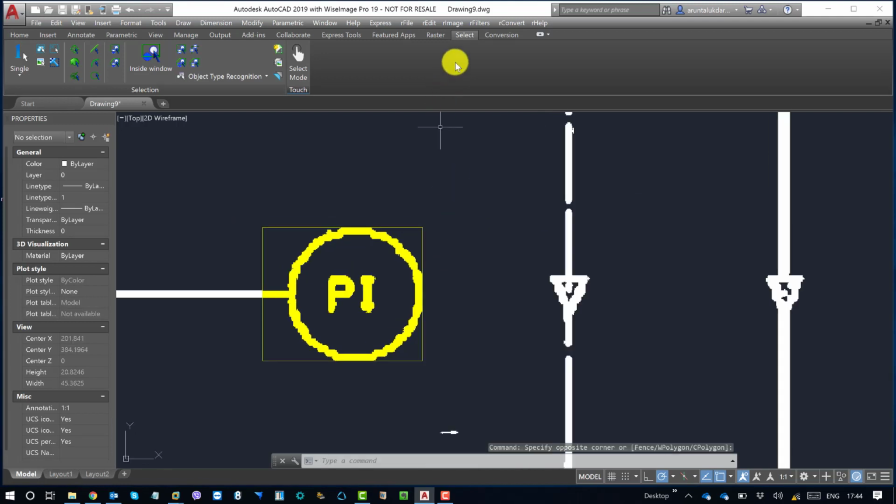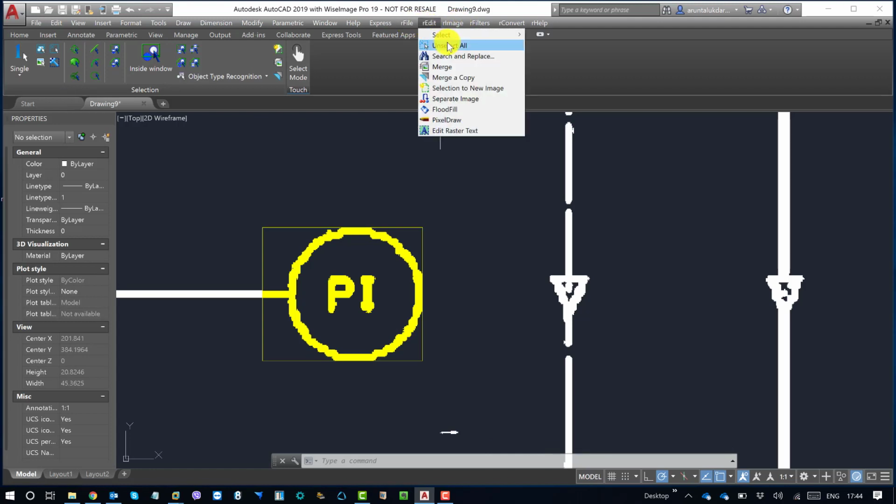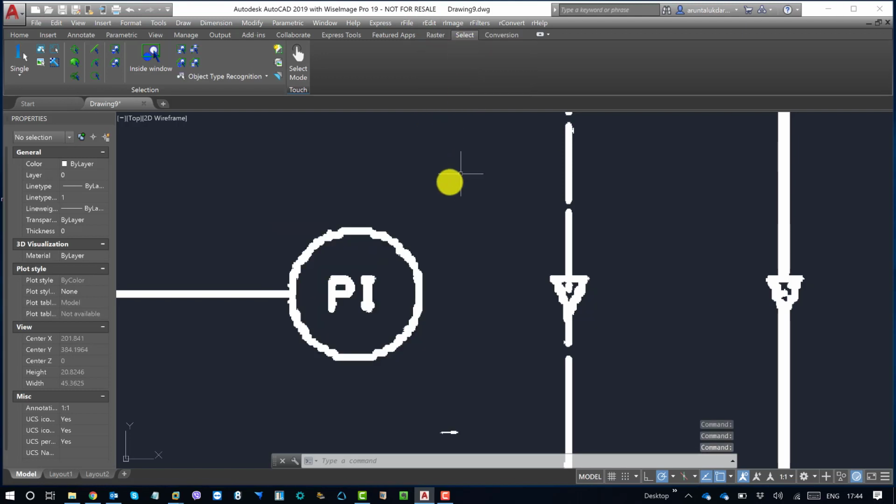If I need to unselect, I have to go to these functions, unselect, or access it from the menu bar. You need to click on unselect all. Only then can you unselect the selected objects in the drawing.